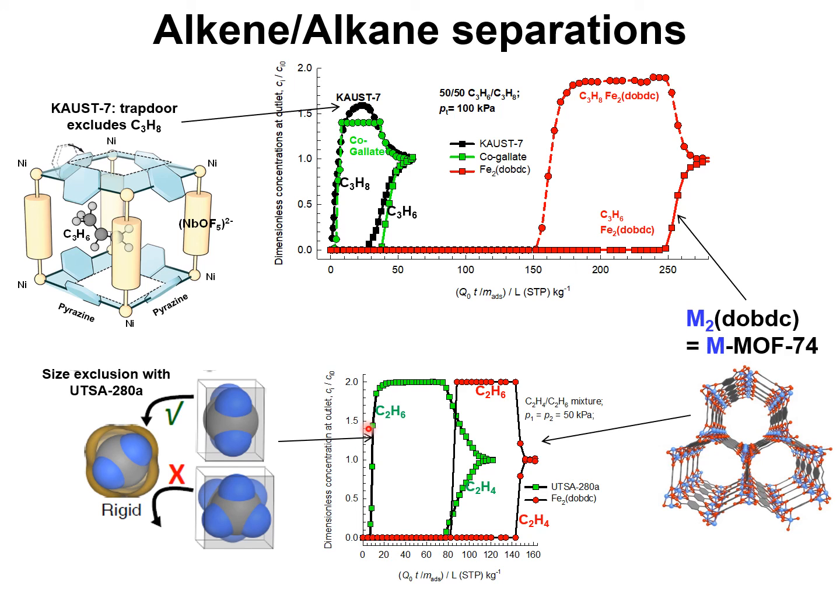So this early breakthrough of ethane is desirable in a PSA scheme because it implies that a negligible proportion of ethane will be present within the void spaces and in the adsorbed phase during vacuum blowdown operations.